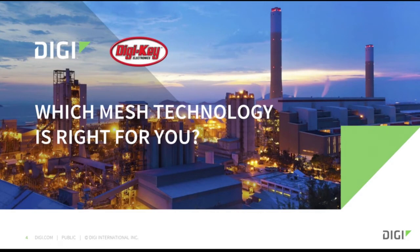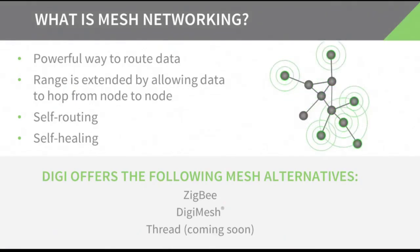It's a powerful way to route data. It allows you to extend the range of your application over a great geographic distance, or even in a building where line of sight or point-to-point communications are not possible. Mesh networks are typically self-routing, meaning you don't have to take care of routing tables. You don't have to know the nodes in each hop of the transmission. All you have to do is address your radio, and the routing is taken care of for you by the protocol itself. They're also self-healing. If for any reason a route becomes no longer usable, the mesh is capable of rerouting itself to self-heal the network.